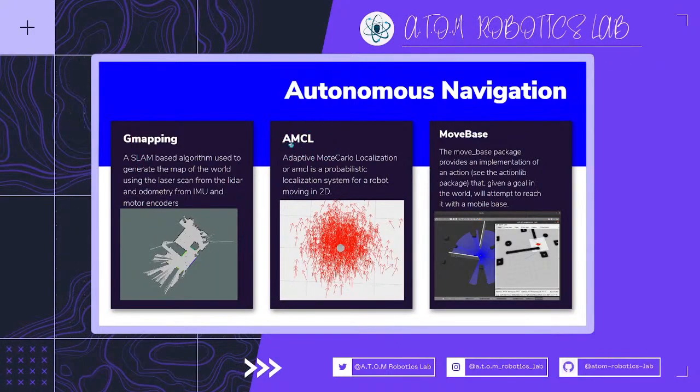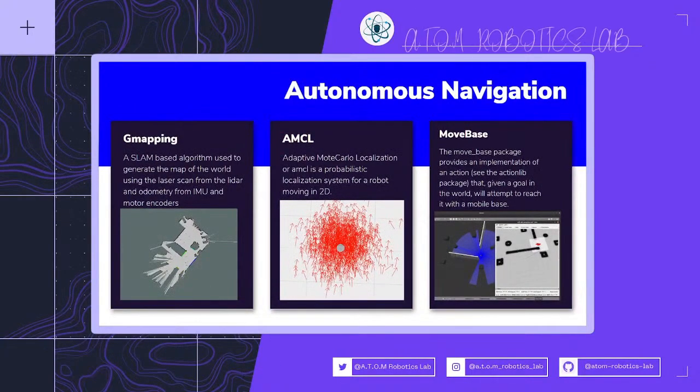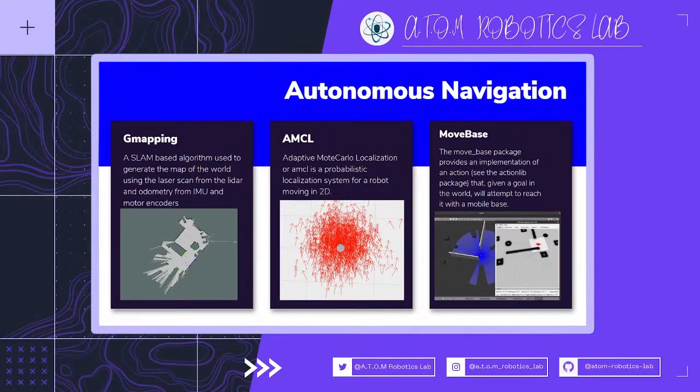Okay, so like Alok said, coming to AMCL. When we create our map for basic path planning, after that we launch the AMCL node, which orients the current laser scan with the map we provided, which helps orient the bot itself according to the map.